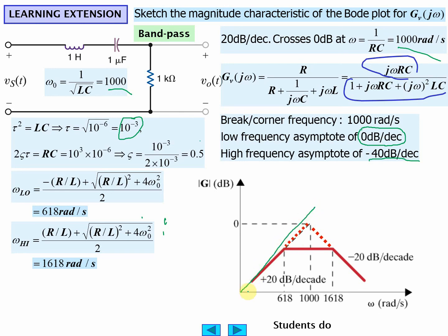So it ramps up. It's a band pass. Ramps up, ramps down. This is a log-log plot, by the way, just remembering that. Decibels are on a log-log scale. And the, let's see, flat line. So these are asymptotes, by the way. Remember, they're asymptotes. The reality is more of a curve, like this. .618, half power low, half power high.